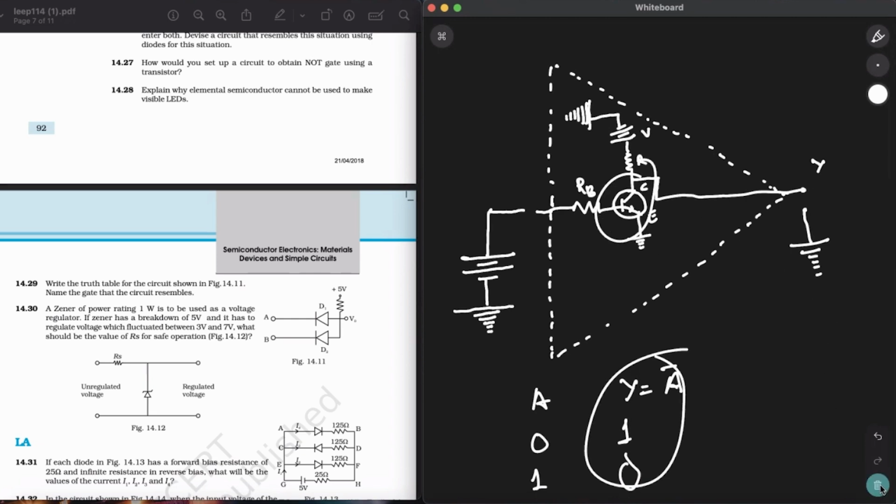See, to remind you of the theory behind this, you have to realize it as a NOT gate. Alright, so the transistor is so biased that the collector voltage VCC will correspond to one state. Now the resistors R and RB will be chosen in such a manner that if the input is low, such as the input is 0, the transistor will be in the cutoff, and hence the voltage appearing at the output will be the same as applied. As applied here, over here will be 5 volts. So in the output you will see 5 volts when the input is 0 volts.